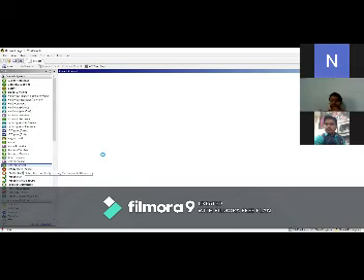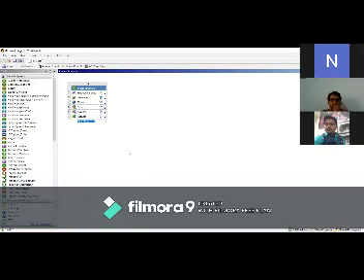When you click on static structural, you can see the static structural window: engineering data, geometry, model, setup, solution, and results. By default, static structural is set. We have to do the piston analysis here, so we put up the piston analysis. Our analysis type is static structural, and the geometry name is piston.